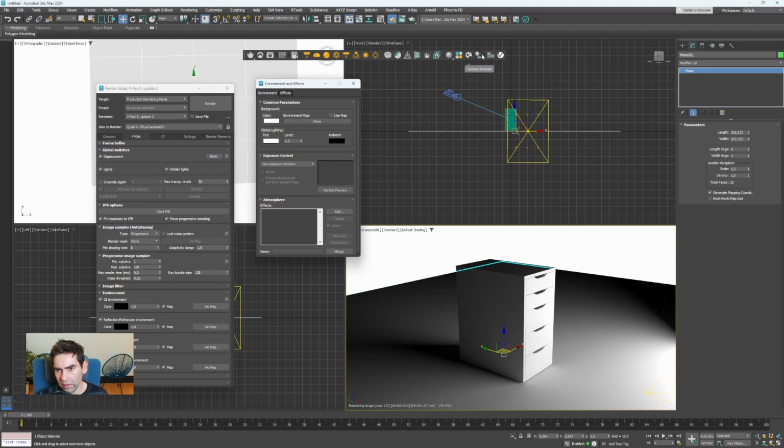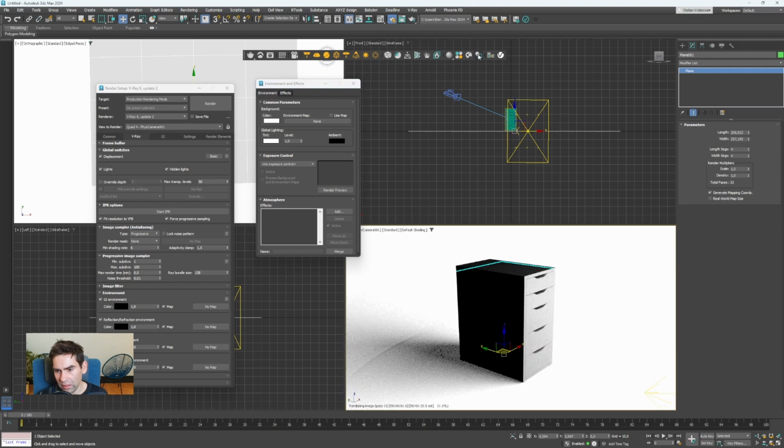The ground plane can be receiving shadows only. So you can click here in the V-Ray toolbar by selecting the ground plane and then clicking on Make V-Ray Shadow Catcher through the V-Ray object properties. And that's what this is doing here. So now it's invisible except creating here a shadow.